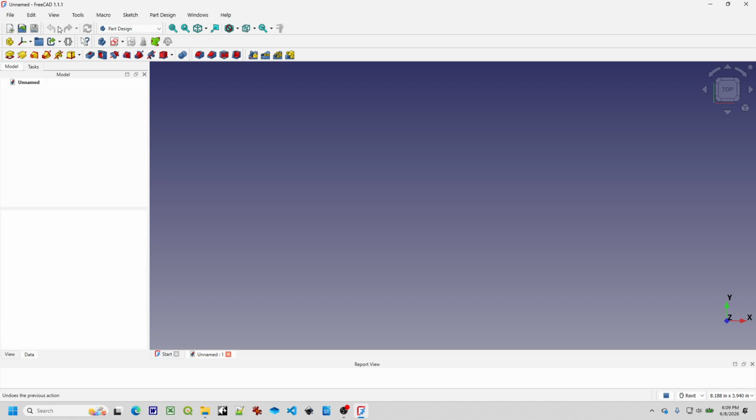So there are some persistent toolbars that stay, just like any software, like there's save and rebuild the model, and this is the measure icon, blah blah blah. This thing's always safe. And then these are more general, high level commands. This is to make a part. This is to create reference geometry. Create an organizing folder within your tree structure. This is to create variables. This is to create a sketch. Sketch, you're going to become expert, hopefully, at doing sketches. They're the fundamental thing before we create a solid model.